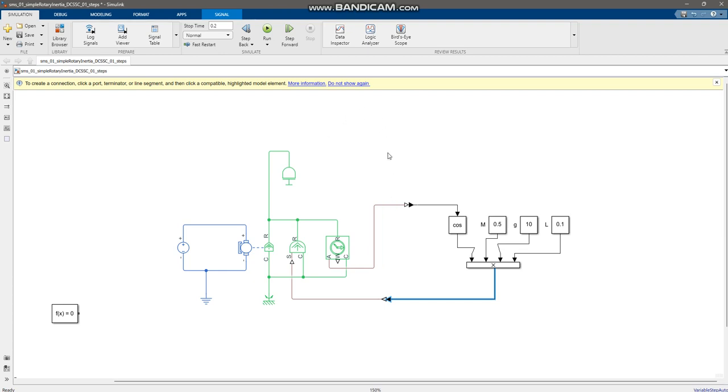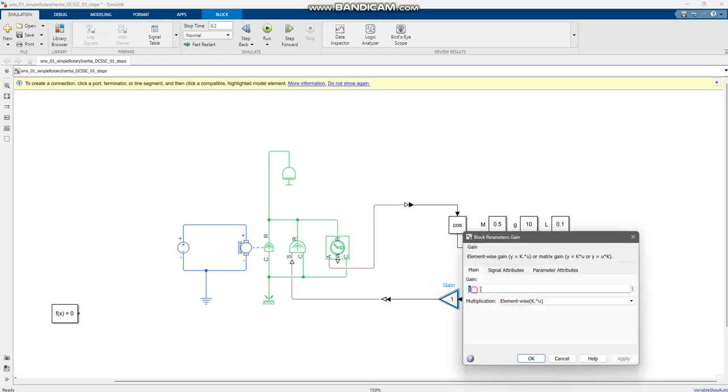So the directions are opposite, and if the counterclockwise direction is taken as positive, then any clockwise torque needs to be negated prior to making the addition. That can be done by introduction of a gain block with the gain set to -1. And I think I forgot to include the -1 in the physical lecture as well. So apologies for that.